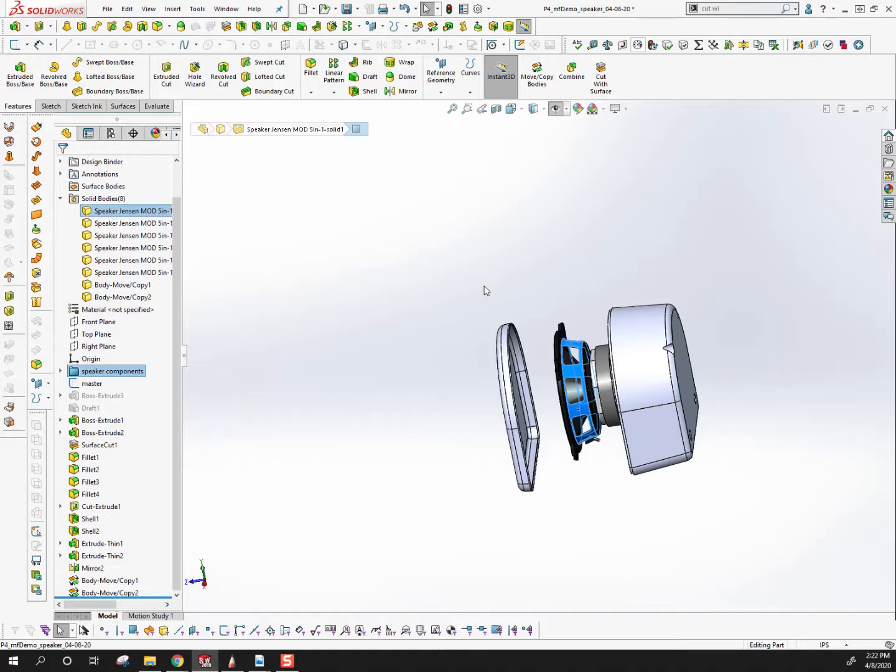Because you can be in an assembly and right-click the part and say edit part and build within the assembly. I believe it's a little bit more taxing on your computer. But if you prefer that other workflow, that's cool too. So you can build a part, put it into an assembly with the components, and then once you're in the assembly, you can right-click on that and say edit. And maybe I can set that up during the break to show you all what that looks like. I don't know if that answered your question.